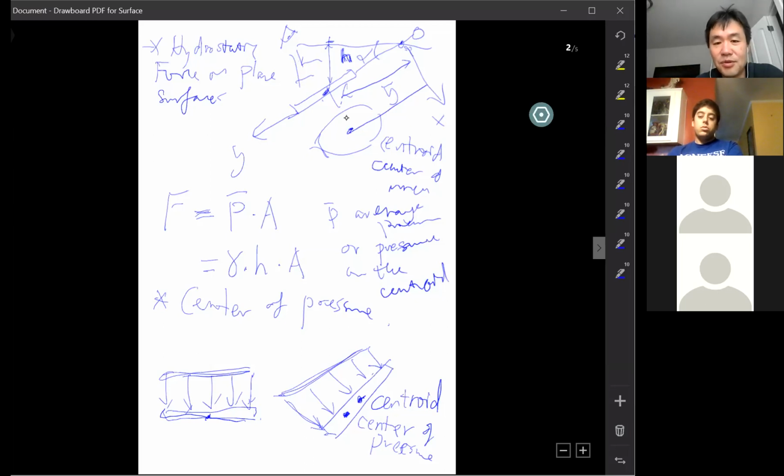Of course, we're talking about the x dimension being symmetric, so you don't have to change anything. If you change the x dimension geometry, then it will be different. We'll only look at the 1D y direction, so I assume the area is about the same along the x direction. Then, sure, your center of pressure is lower than the centroid. It's always lower.